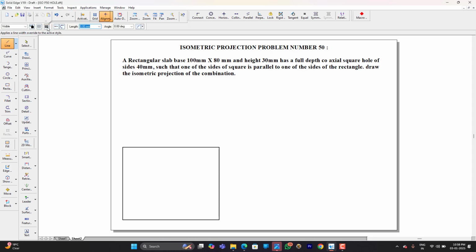Next, I'm going to project this in the front view. Here I'm going to draw an XY line. I'm going to label it as X and Y on either side. Here this side I have X and this side I'll have Y. And here I am going to represent VP, vertical plane, and here I'm going to represent HP, that is horizontal plane. So anyways, I have to project.